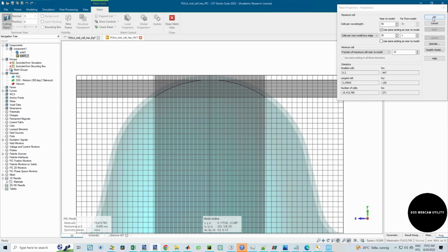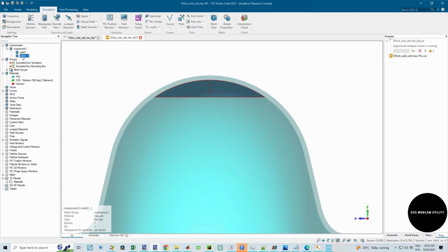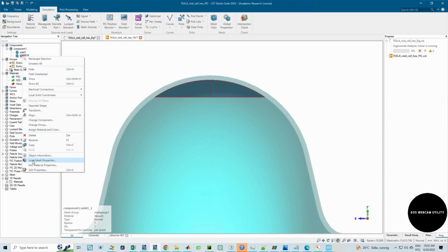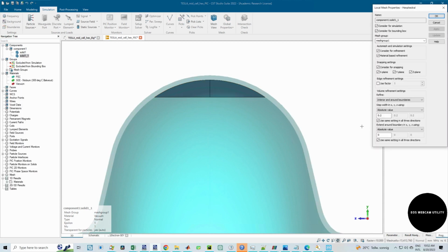I hope even with a bit coarser mesh I could have the multiplexing result, otherwise I'll just show an old result. I don't want to run this for a very long time. So 6.9 million, a bit manageable. Let me make that 0.35. This defines the maximum step I think I already mentioned. So a millimeter, so 0.35 millimeters, 5 million.